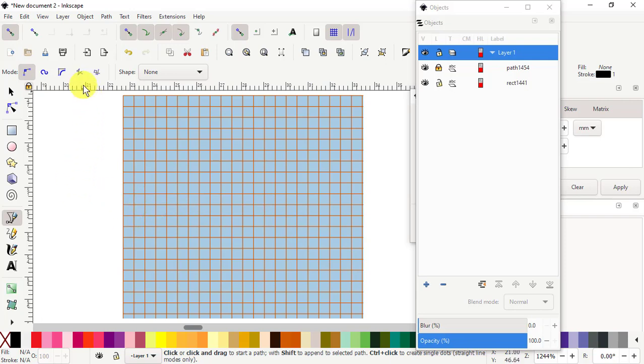If you want more guides for helping you out with it, you can snap guides. You can also say, I want to have one on the center line. Then I can pull a guide down that way, and draw a guide this way, and put them on the center.